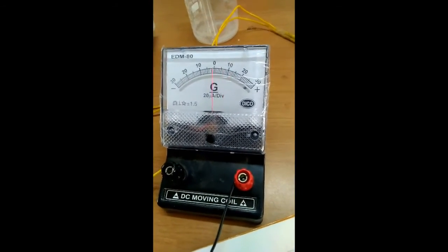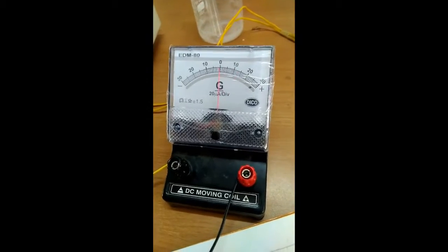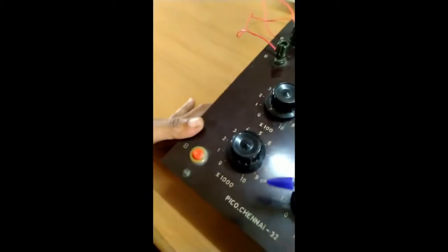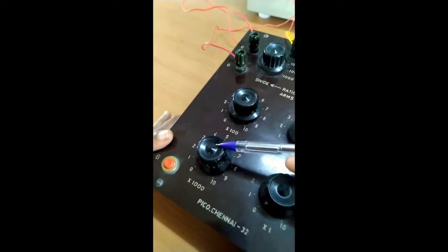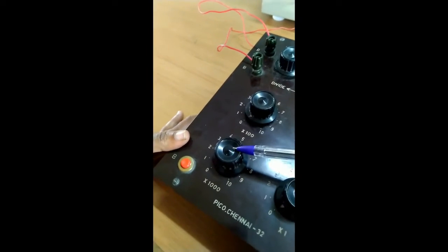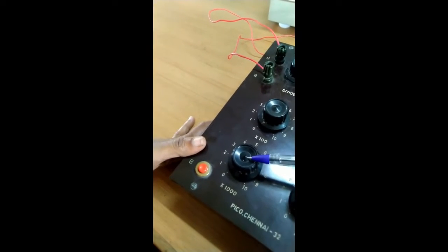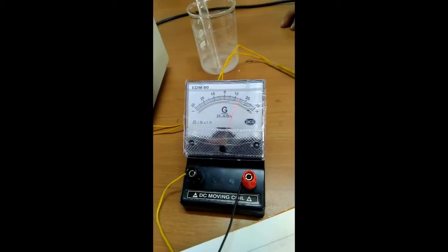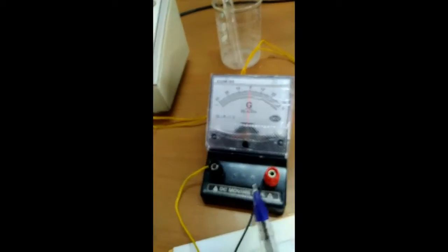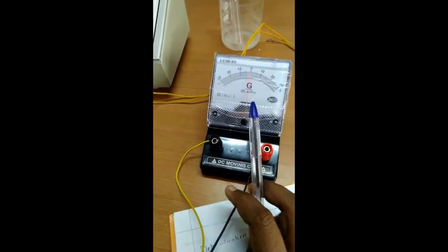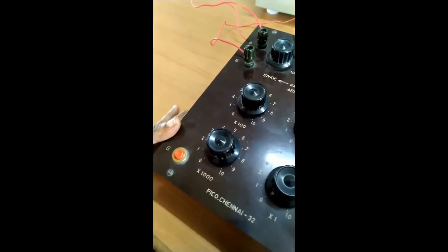Check the deflection in the galvanometer, it is to the right. Now there is a change in direction. For 0 in the 1000 dial, the deflection is towards the left. For 1000 in the 1000 dial, again the deflection is towards the left. And when you move this dial to 2000, the galvanometer shows a deflection to the right side, right? So there is a change in direction from left to right when you raise the resistance from 1000 to 2000. So whenever there is a change in the direction of deflection, you need to keep this dial in the previous position, right?